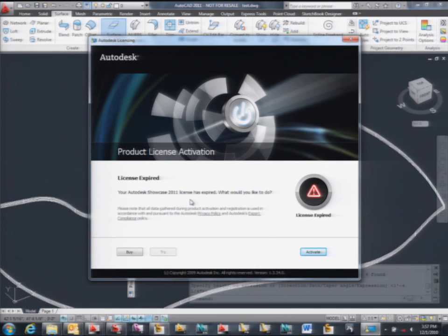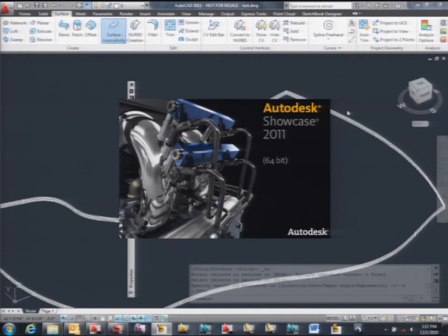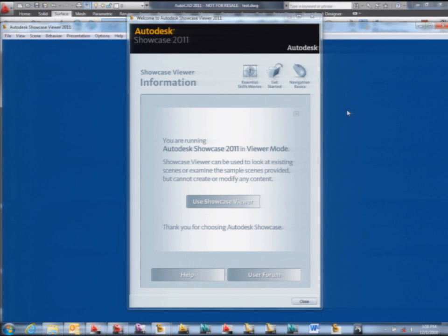Yeah. When you make those real complicated surfaces, is there a way to unroll them into a developed surface? Yeah, I got that question before. No, you can't in AutoCAD. You should be able to do that. I mean, for example, if it's sheet metal, you could do it in Inventor. There's a plugin for Rhino that is supposed to already be there for AutoCAD, the Teraflat. Yeah. Isn't that one? I can't remember what I've done it. Yeah, right. So, yes. The answer is there are ways to do it if you have the right plugins, as usual.